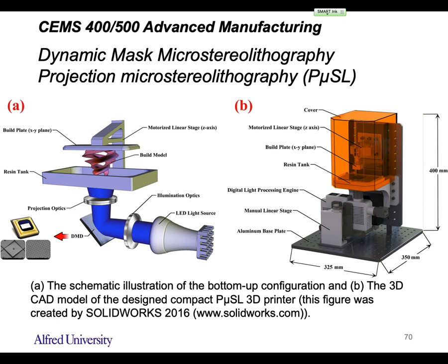So if you have the projection-based system, I got this from the literature. You have to work on your projection optics. You can simplify it by focusing that image. We have this focusing lens in the projector. If you reverse it, you will just focus rather than enlarge it, right? But you also have to work on the focal length. You want to make sure you have enough work distance for your machine, right?